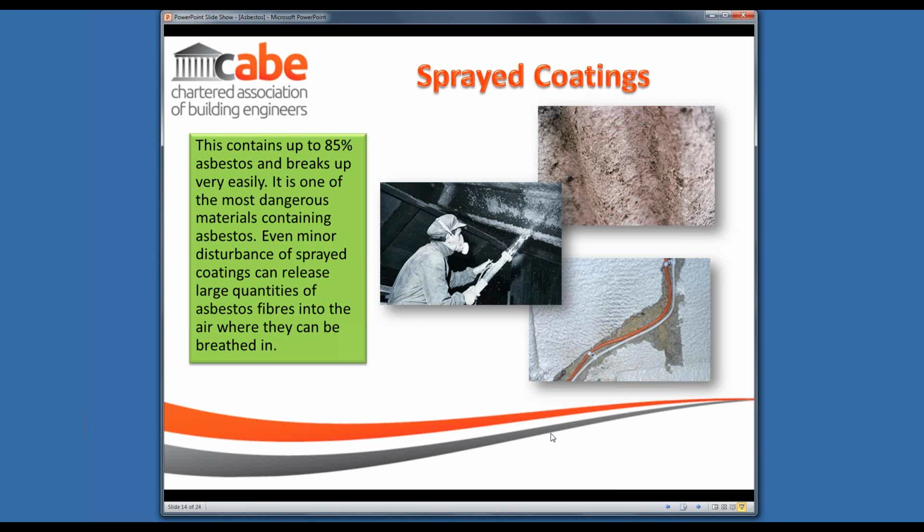And a lot of it, particularly when it comes down to how we control work on asbestos, comes down to how extensive the work is and the duration of the work. So if this work was being done in a well-ventilated area, if the drilling was linked to a vacuum cleaner device and appropriate masks were being worn, then the risks are fairly low.